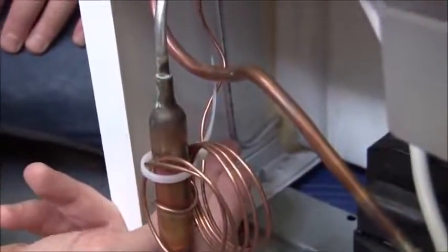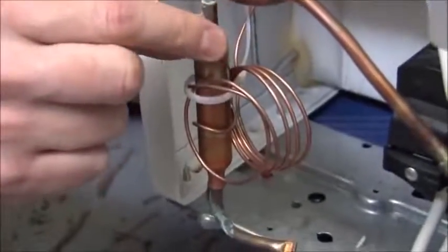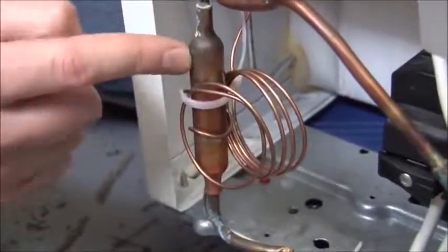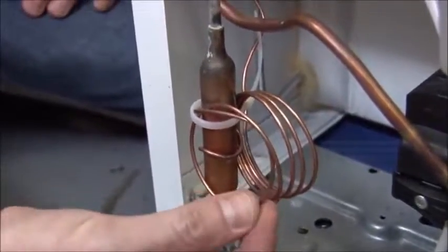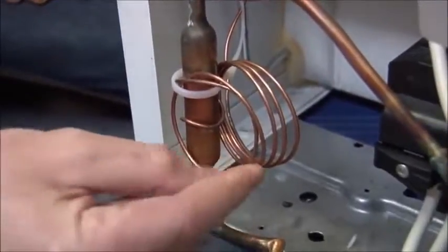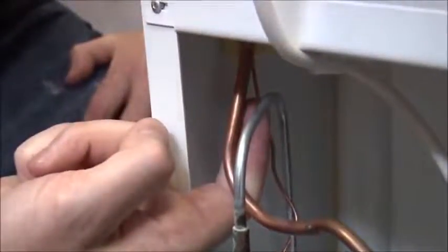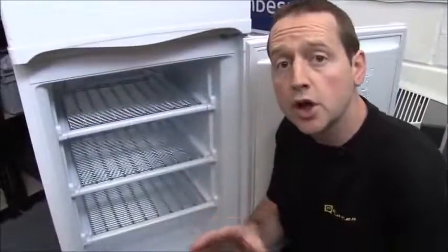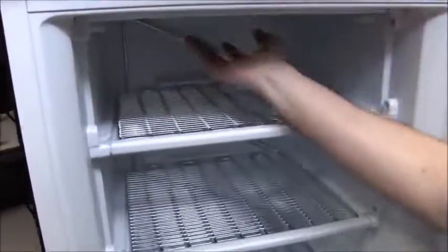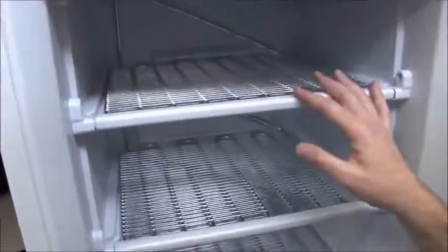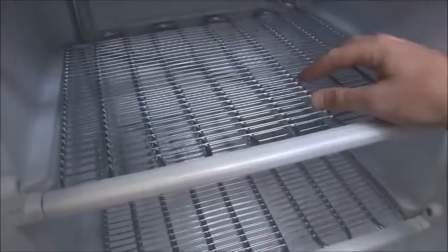Our liquid refrigerant then passes into this thing, which is called a filter dryer, and that just traps any contaminants, removes any moisture, which is important because the refrigerant now passes into this, what looks like a wire. It's actually a very fine capillary pipe, and that feeds up to the inside of the fridge to the evaporator coils. Now on your fridge or freezer, you may not be able to see the evaporation coils. They're probably behind a panel at the back or in the top of the unit. But on this Hotpoint fridge freezer, you can actually see the evaporation coils here. They form part of the shelf structure.